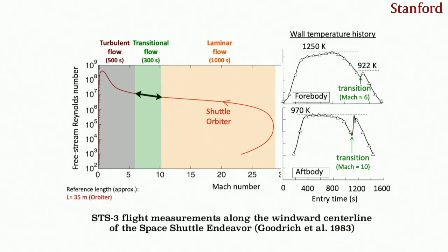And you can see that the temperature increases to a peak value of 1,250 kelvins. And that increase is obviously due to a stagnation point heat flux, to the heat flux across the boundary layer, even if it is laminar, and that caused a lot of temperature increase in that part of a spacecraft.